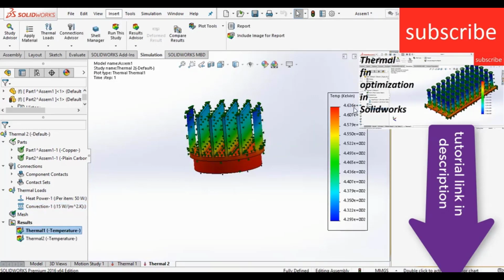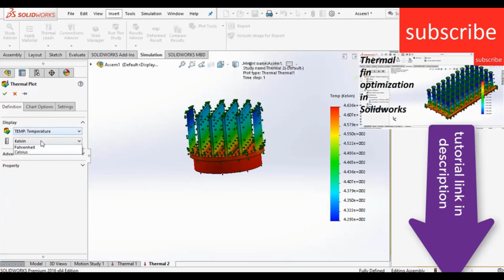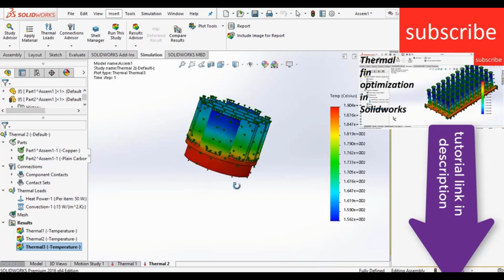Here you see, now I got the temperature results. So let's change the thermal plot again. Click on Celsius, click OK. But here I got the correct result this time. So the bottom part is 19 degrees Celsius and the topmost part is 15.062 degrees Celsius.